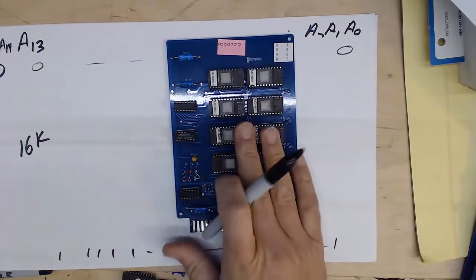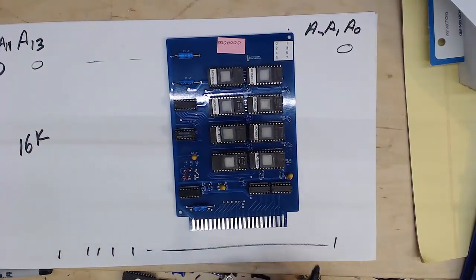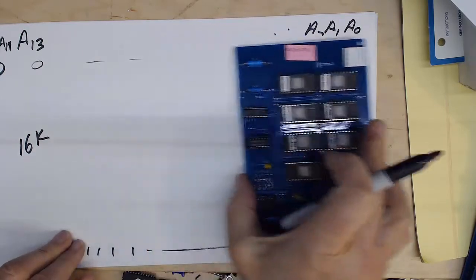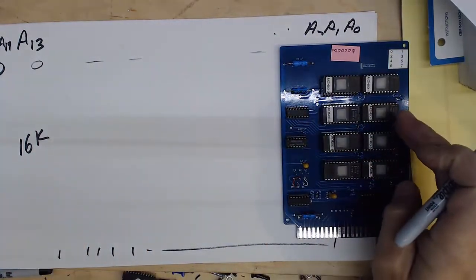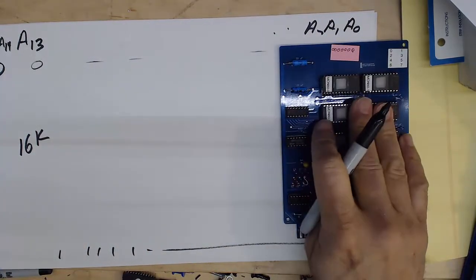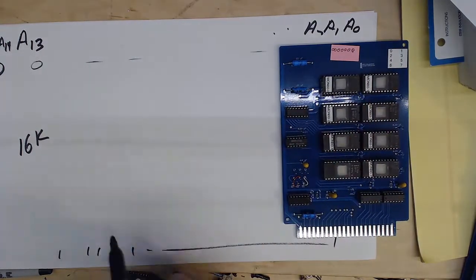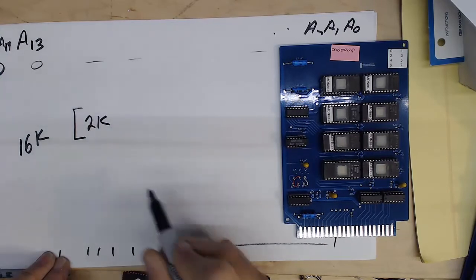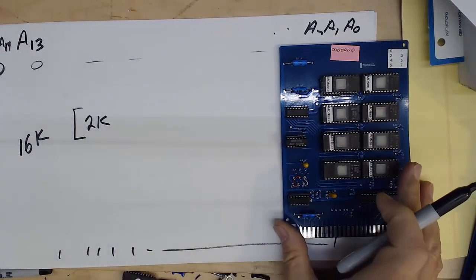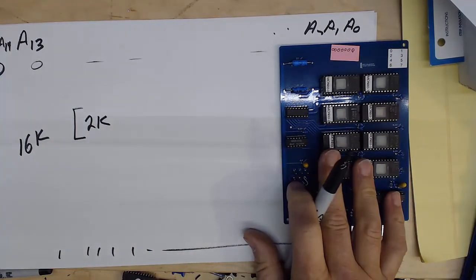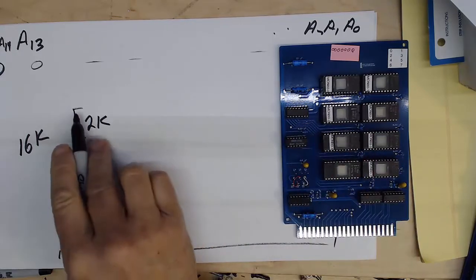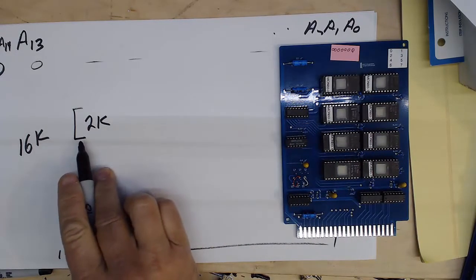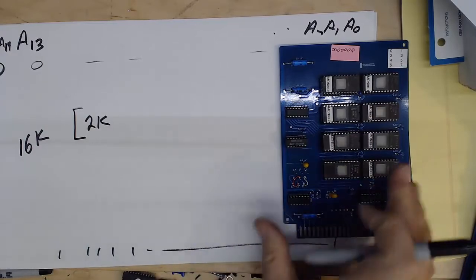Okay, so first we're going to do this, which is the 8-4 ROM. What we want to do is map this somewhere into our memory. And of all this memory, we need to have a little 2K block that is just dedicated to this card. So nobody else turns on except for this card anytime we're within that 2K block. That's what we mean by this memory mapping.